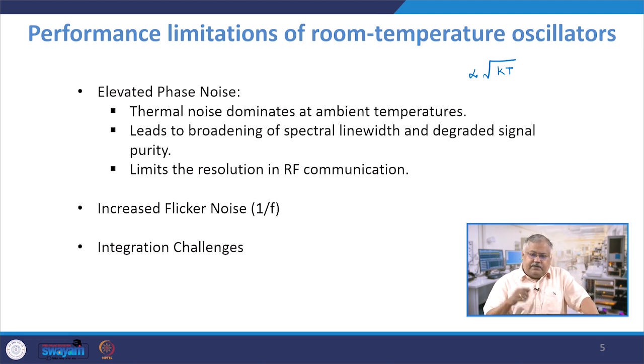Flicker noise is also referred to as 1 by f noise, and it is inversely dependent on the frequency. So, the higher the frequency, the lower the noise. If you are operating at relatively low frequency, of the order of a few kilohertz or so, you will also have an increased flicker noise. Not every time do you operate at very high frequencies, but fortunately for quantum computing purposes, these operate at a few gigahertz. At these high frequencies, there is a reduced flicker noise at cryogenic temperatures, but at room temperature, they play a major degrading effect on the oscillators.